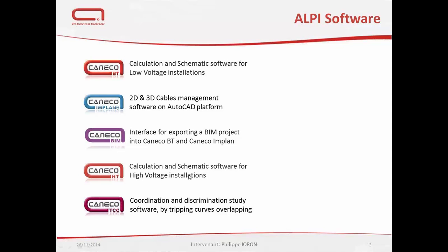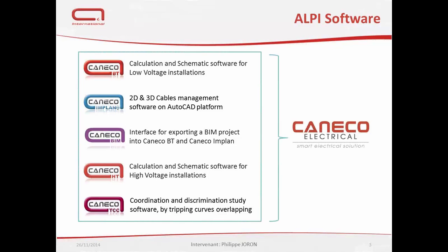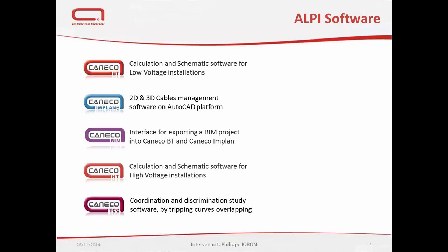It's a graphical software which allows you to get the tripping curves of different equipment for high voltage and low voltage installations. Thanks to that, you can set your protective devices very easily, and you have all the information for the setting of the equipment. All of this software we call Caneco Electrical.